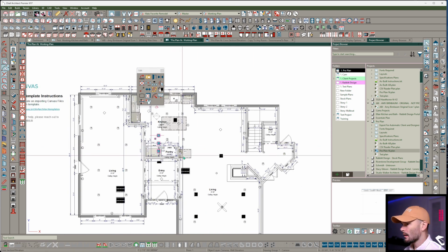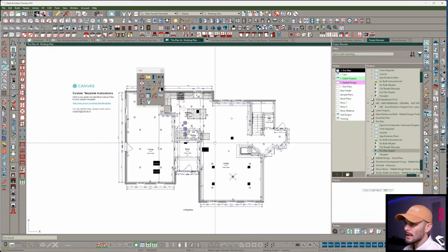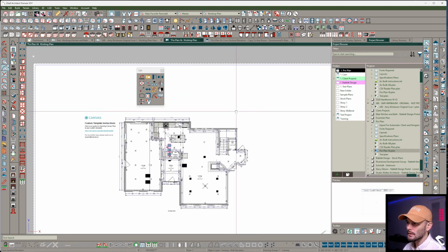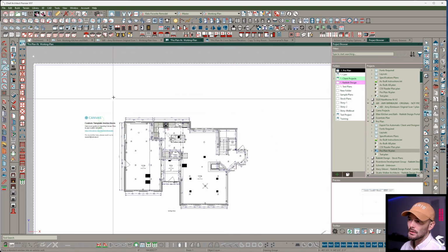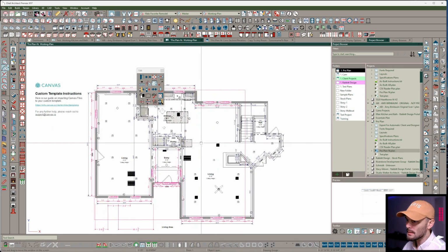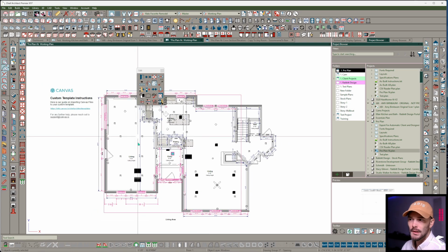Okay, now what's up next? We need to conform all of our cabinets, all of our windows, all of our doors. So we're going to use the window tool, just do a little marquee over everything. This is just one way to select all your windows. We want to make sure that we're not selecting any mold units. Mold units can be problematic.